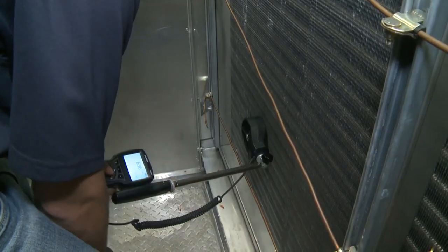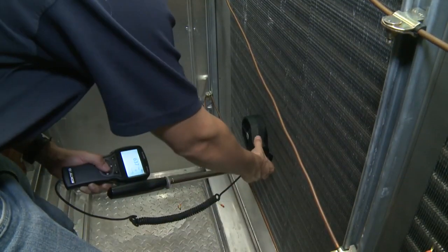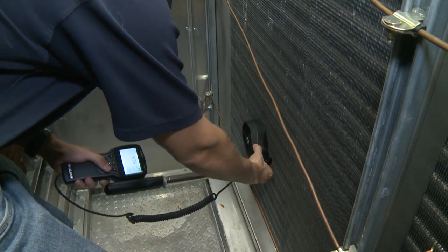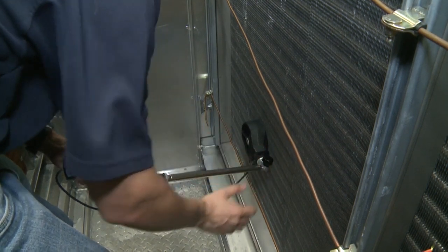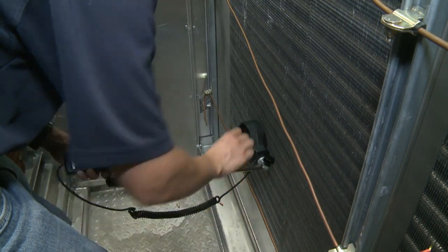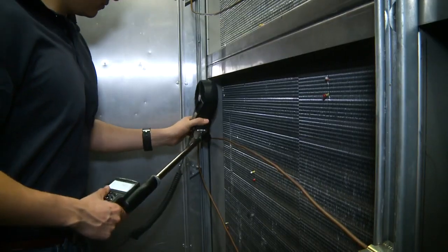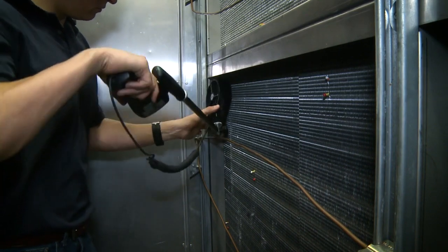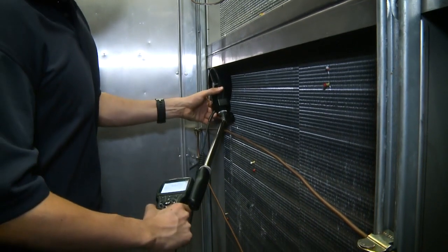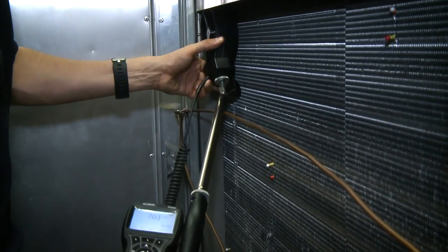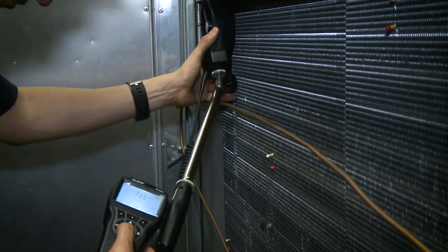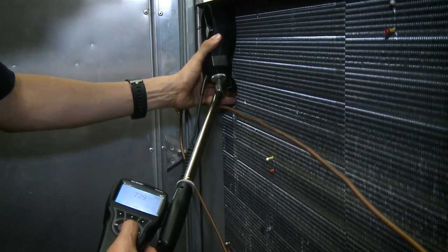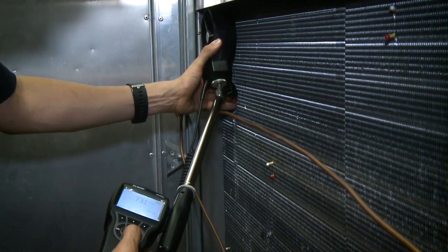The following video films the bottom coil traverse. However, in the field, both top and bottom coils were traversed for 38 position points each. Starting with the standard velocity reading location, position point 1, place the vane anemometer's head centered over the position point 1 intersection, and lay the vane head flat to the coil. Wait a few seconds and record the reading in feet per minute.